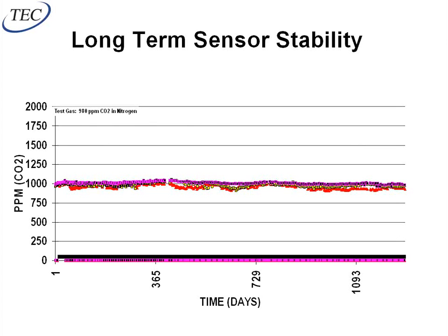You can't go in and calibrate them anymore. Some of these manufacturers have actually removed the calibration button because they don't want people to calibrate them anymore, because you actually do more harm than good when you incorrectly calibrate them. So if you have one of these types of sensors from one of these manufacturers like Telair or Carrier or Honeywell, what actually ends up happening is if you have to calibrate it because something's wrong with it and drift it out, you actually return it back to the manufacturer and get a new one under warranty. And that doesn't happen very often.